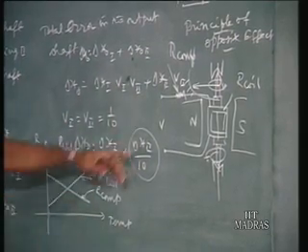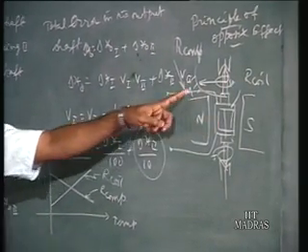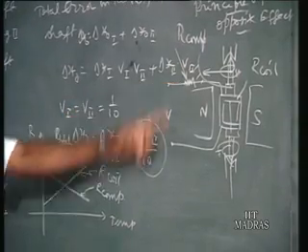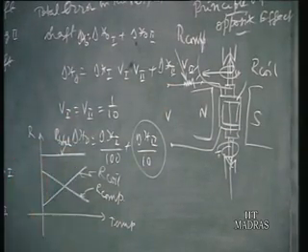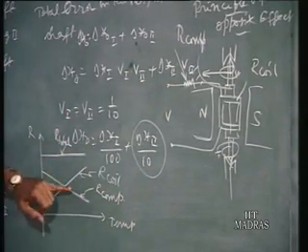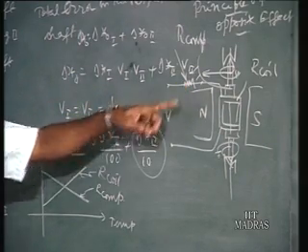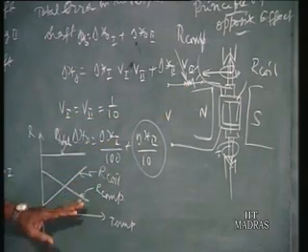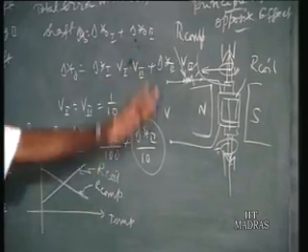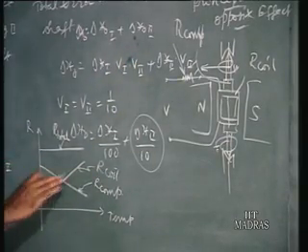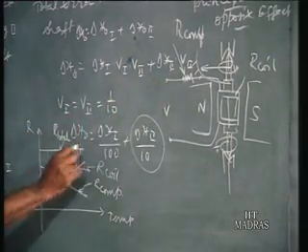Now to the extent the R coil resistance is increased, to the same extent R compensating resistance is decreased, so R total remains the same. Now that is the opposite effect. We have to select such a compensating resistor which will reduce the resistance to the extent R coil has increased due to temperature. That is the opposite effect. Put the opposite effect in series and R total remains constant.